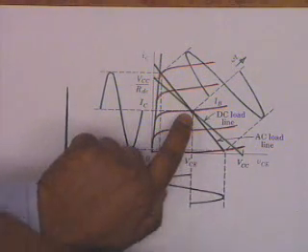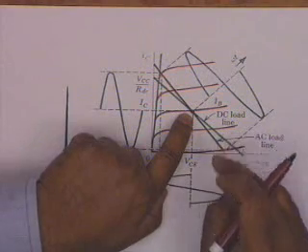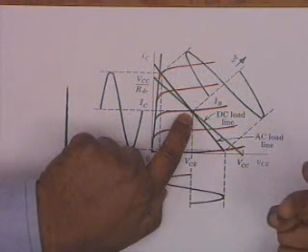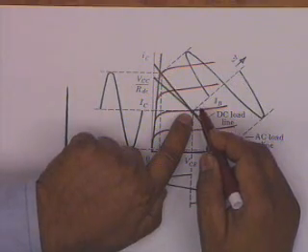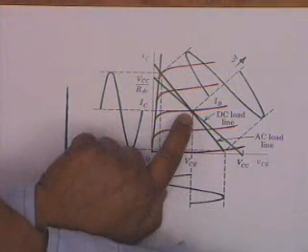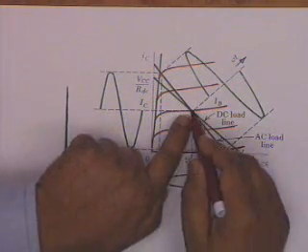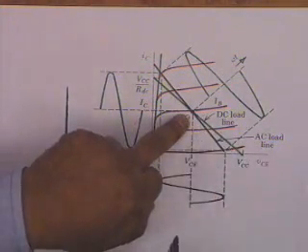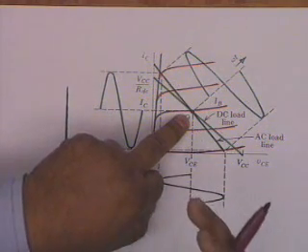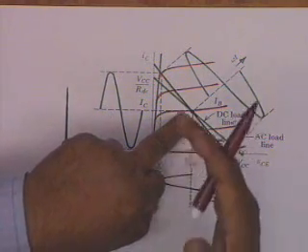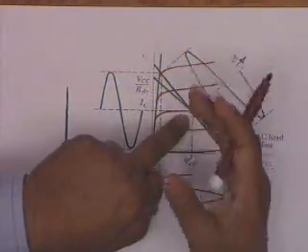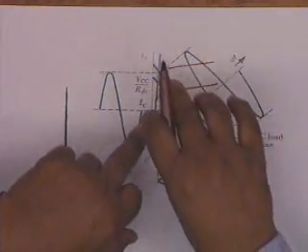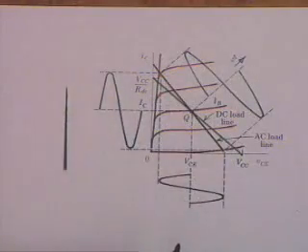That's correct. At this point, the input signal current is 0. This is the DC quiescent point. DC quiescent point is also the AC quiescent point. Therefore, once you settle on the DC Q point, the AC load line hinges on this point and goes slightly above. That is, it goes slightly in the clockwise direction.